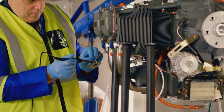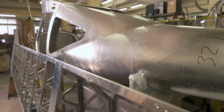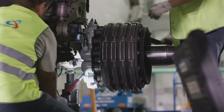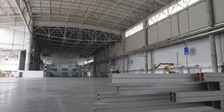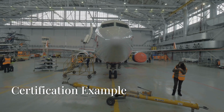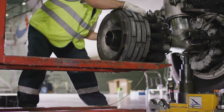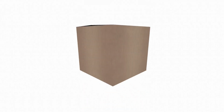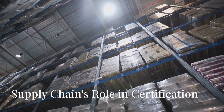Every part used on an aircraft must meet strict airworthiness requirements. Parts have to be traceable to a certified source, supported by an EASA Form 1, FAA 8130-3, or something equivalent. And of course, they need to be properly stored and handled to avoid contamination. So, for example, a batch of bushings received without proper paperwork is quarantined, investigated, and returned to the vendor, even if the part itself is technically correct.